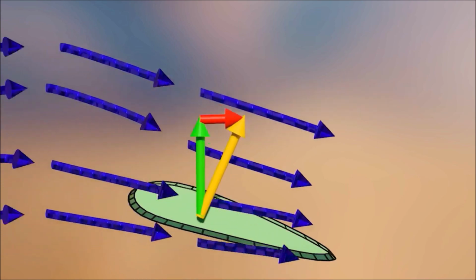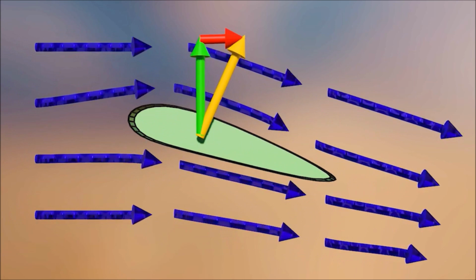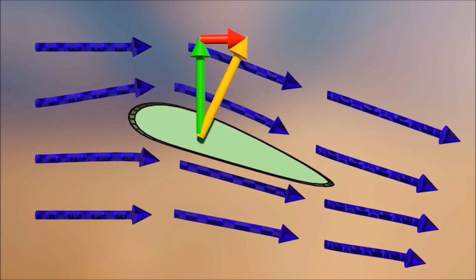Okay, so now on to speed and how it affects induced drag. As we move slower, we have less airflow over the wings, but we need to continue producing enough lift to balance our weight. To do this at lower speeds, we need to increase the downwash.